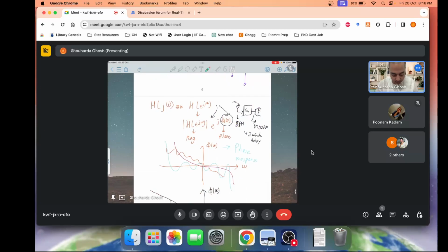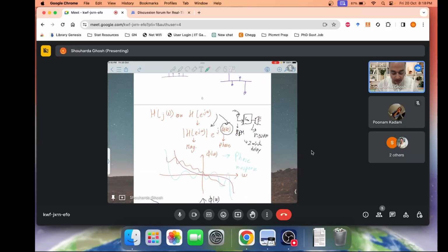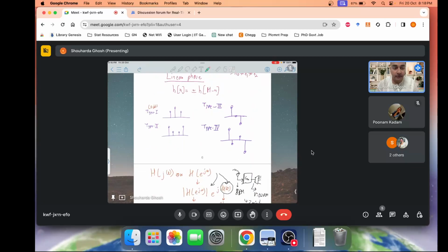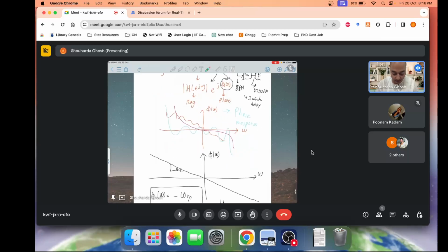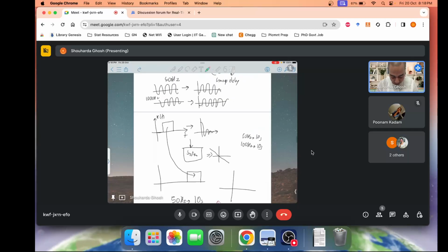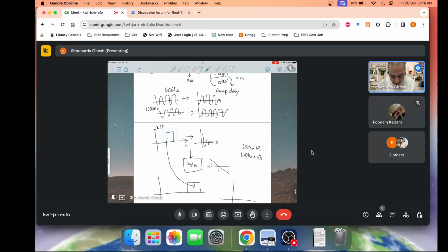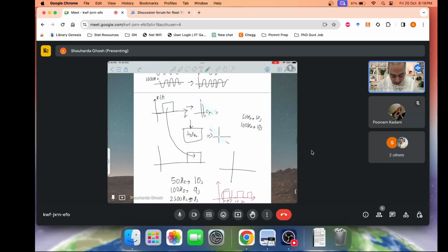So what happens if the system is a linear phase system? In real life your signals will have multiple frequency components, and you would like to ensure that all the frequencies get delayed by the same time. If there's a pulse with a sinc response and the system is linear phase, then the corresponding frequency components will have equal time delays.